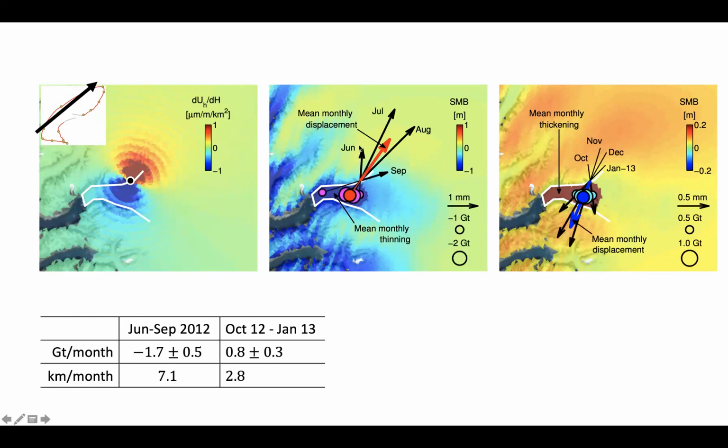So basically going from June, July, August, September, it was like a clockwise motion of the bedrock position, and the corresponding centroid of mass is really traveling down glacier. And the same is true in this case. So remember that in this case, the mass anomaly is negative because it's ice thinning. That's why the GNSS station is pointing away from the negative mass anomaly. But in this case, it is positive. That's why the GNSS station is really following the direction of the positive mass anomaly.